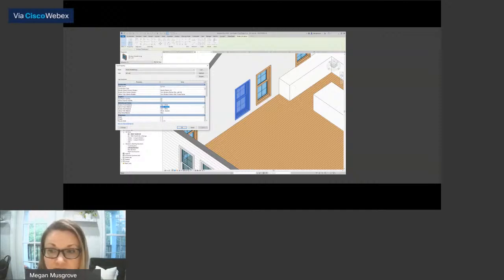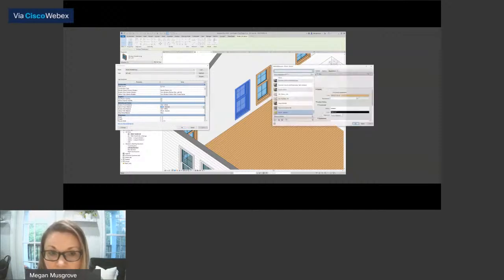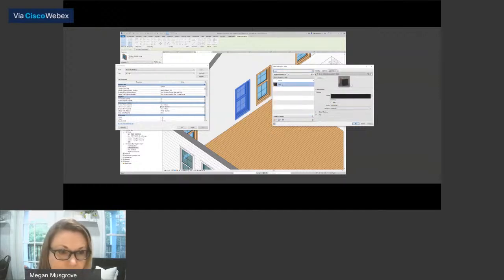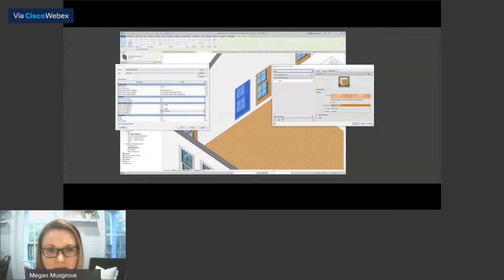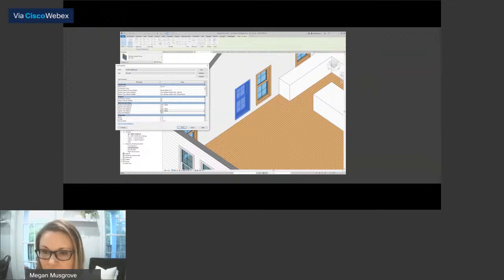We're going to click on that for interior frame material. We're going to click the dot, dot, dot, and we're going to type sash. There we go. And then we are going to turn the interior trim material to be the same, that clad white. That's okay. And then we're going to hit OK.